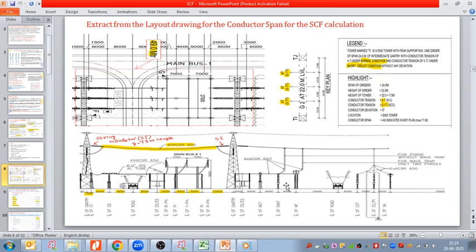So that is why near the point of connection we have used separate metering CT and VT. It is required by the client, so we have provided separate metering CT and VT here, and then the wave trap, and then here we have connected with the transmission conductors, and here we have the CVT and surge arrestor. So we have taken the drop for that.